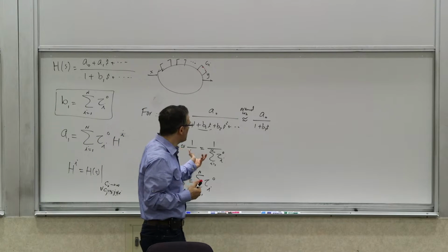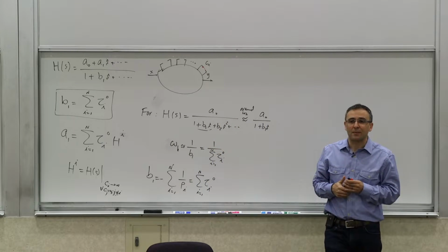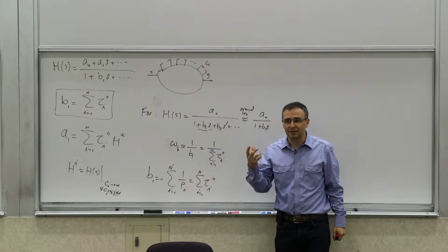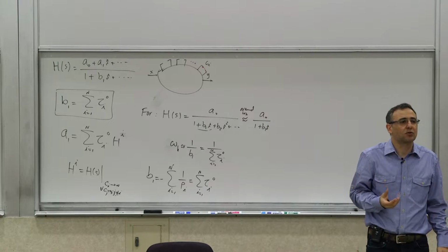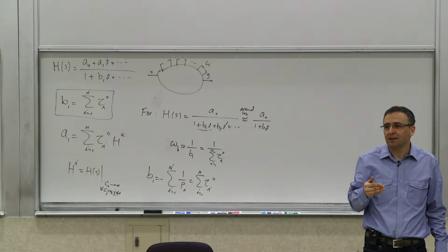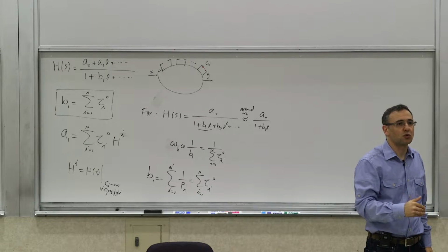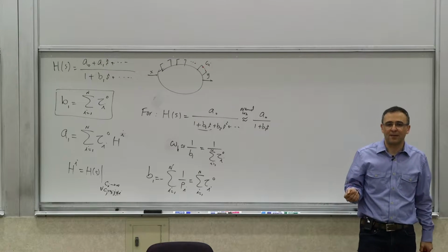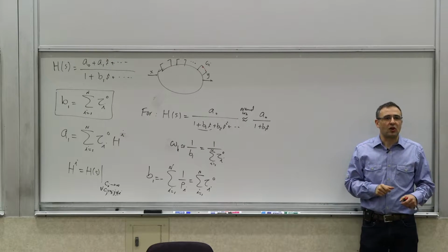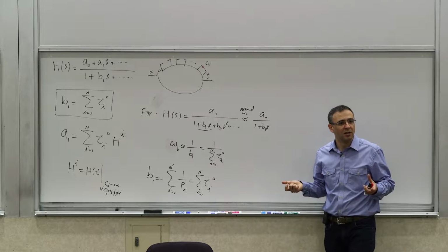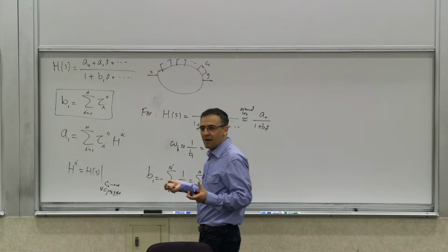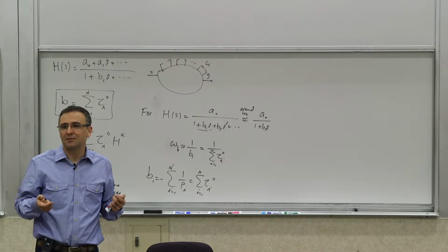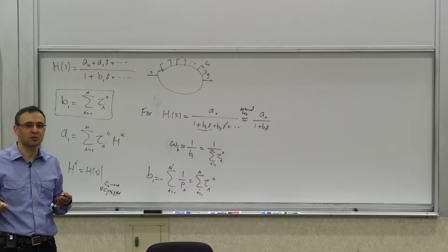And we did use this as a way of approximating. The major advantage of that is that you can actually write these time constants independently in a circuit. It's a design tool because it allows you to evaluate these zero value time constants independently and use them to identify where the major source of bandwidth degradation is and use that to enhance it. And we saw a design example, right? We went from a basic common emitter, and we saw that we were dominated by tau mu in that case because of the Miller effect. Then we went to a cascode. We reduced that time constant. Then we were limited by the load capacitance and the load time constant.